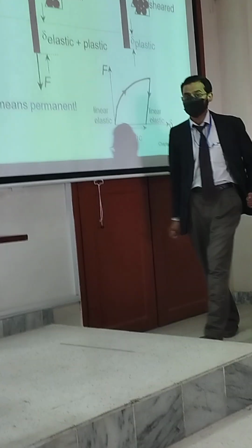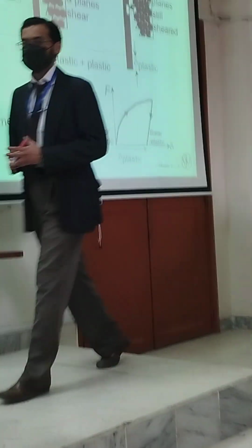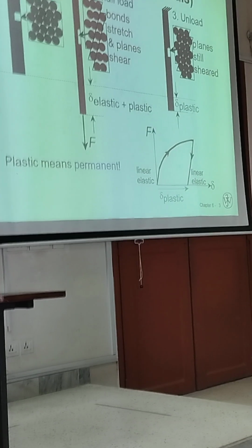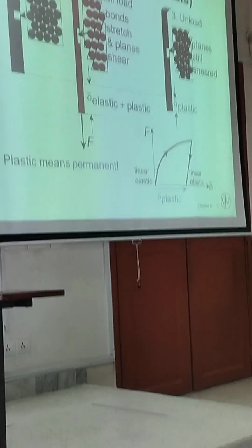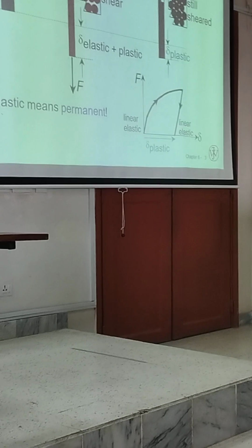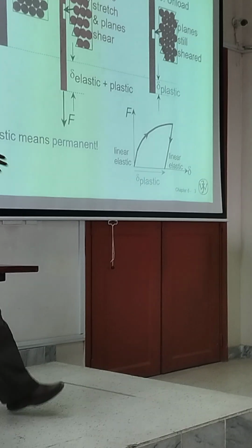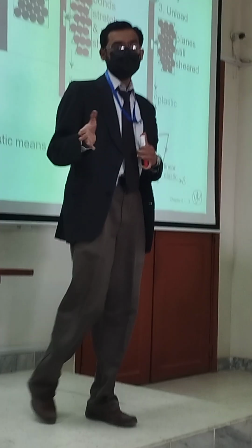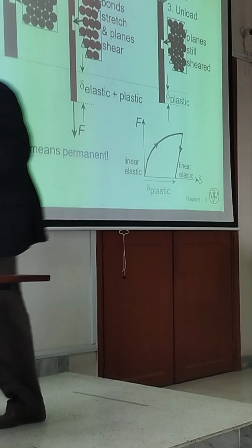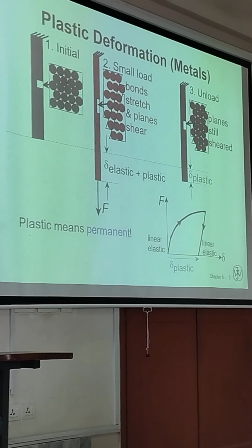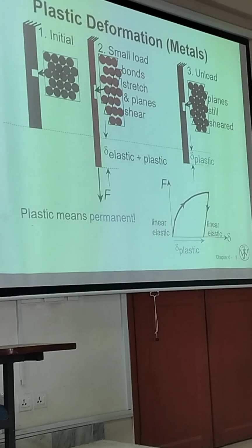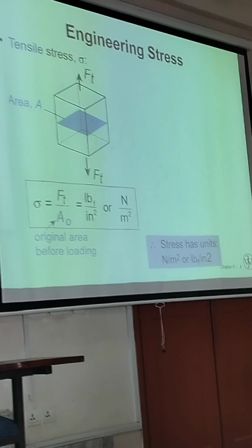After that there is going to be deviation from the straight line, and the point where it deviates is known as the yield point. After the yield point, plastic deformation is going to start taking place. We've also seen that it is humanly impossible for us to pinpoint the yield point, so we have certain criteria associated with that. We'll discuss that later.